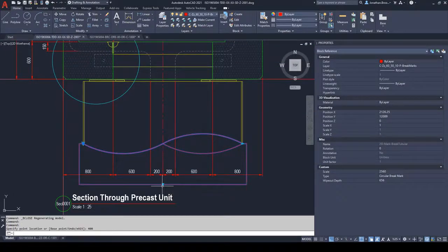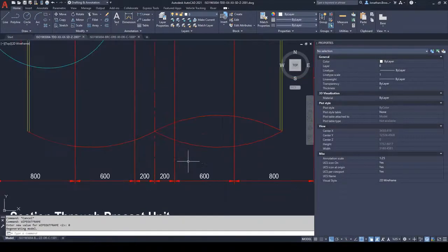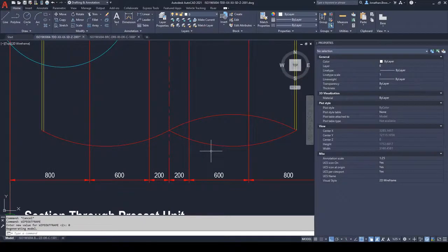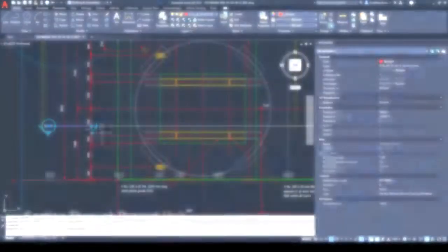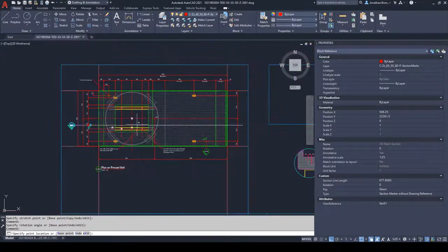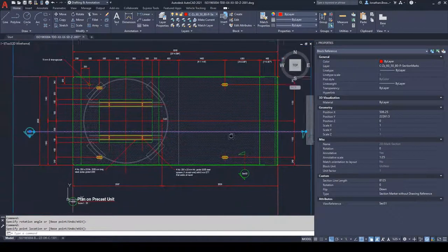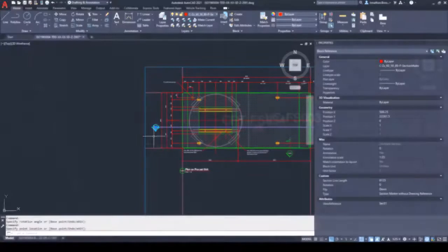It is useful when applied to parametrically altering symbology, such as the depth of a wipeout element inside of a brake indicator, or for the distance between two section mark indicators. Users can even mix and match action parameters. For example, a stretch parameter can be rotated using the rotate action parameter so that the stretch can occur in any direction defined by the user requirements.